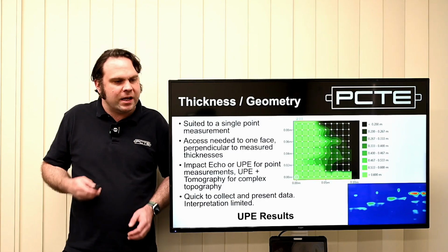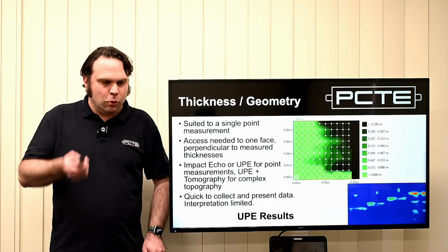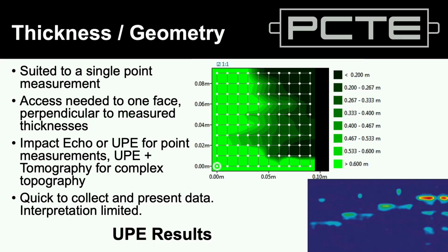Same thing, pulse echo this time. So we do have thickness on a grid as one option. But I know I've got some red in this. That's because I'm presenting intensity data. One of the areas we tend to step back from this a bit, and you see this with our migrated view, when we want to interpret amplitude as well as position, we might use a blue to red just to show that the red is a louder sound, or in this case, a stronger shear wave reflection. And that makes sense, it's closer to the surface.